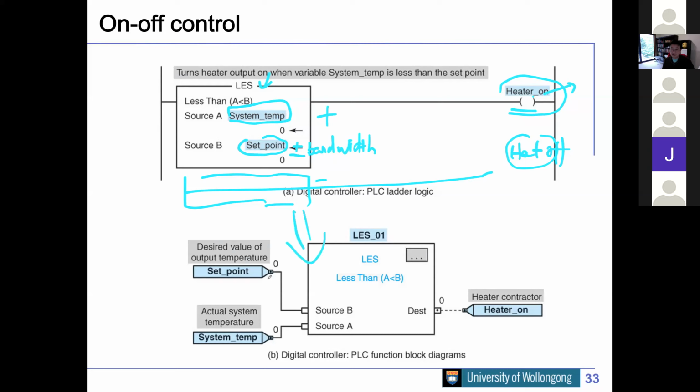So basically you have two inputs. One connects to your setting value. The other one connects to the temperature measurement. So this all goes as the input to the PLC. This is normally just a value inside your PLC. This goes to the output of the PLC to control the relay. So it's very easy to implement compared to, say, PID or even other more complex controllers.